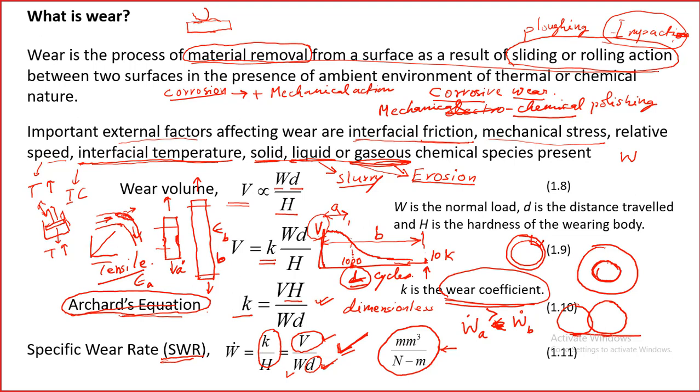Yes, necking will happen, and necking is concentrated within an area here, within some volume of the material. It doesn't happen uniformly. So even though we assumed there would be uniform deformation, because of necking it became localized. This is called localized plastic deformation. So this will happen here and here as well.